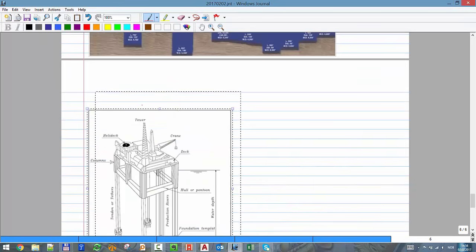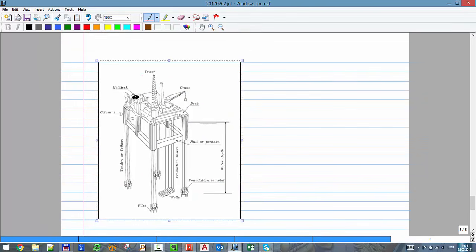It's buoyant, it's floating, but you attach it to the seabed and pull it down. Or better said, you first fix it in place and then you remove the ballast, and it will want to float. If you don't have those lines, it will want to go up and float very close to the surface, but you keep it in place using these lines that are all the time in tension.